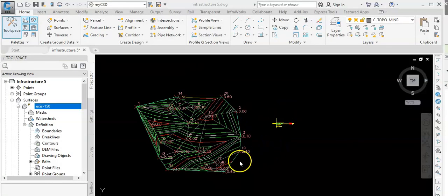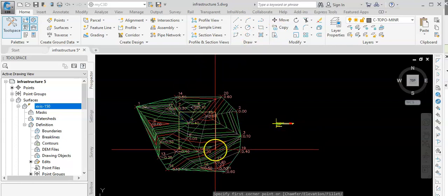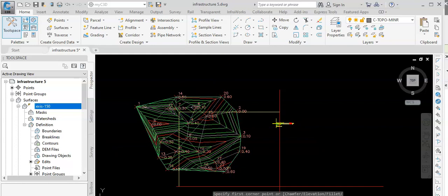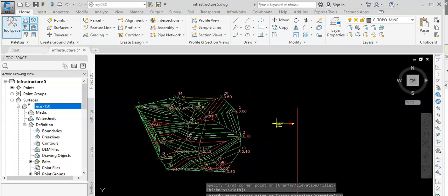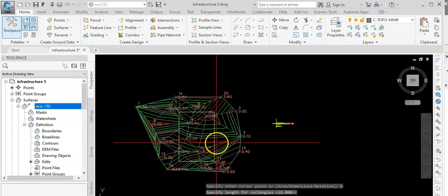So let's transfer these figures into our earthworks model. I usually input the exact coordinates of the building, so it will be plotted exactly on the model. But for simplicity, we're just going to put the size of the building somewhere right in the center here with the right dimensions. What we said is 18 meters by 27 meters.